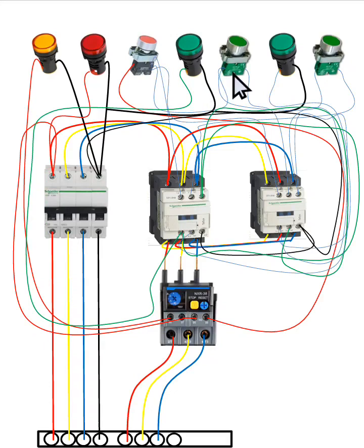You cannot just switch from forward to reverse immediately. If you're on forward and you want to go reverse, first of all you press the stop button, then you press the reverse button. This is the power light. When there is power in the circuit, this light comes on, and when the circuit trips off, this light will also come on. So this practical diagram is made up of the power and the control diagram.